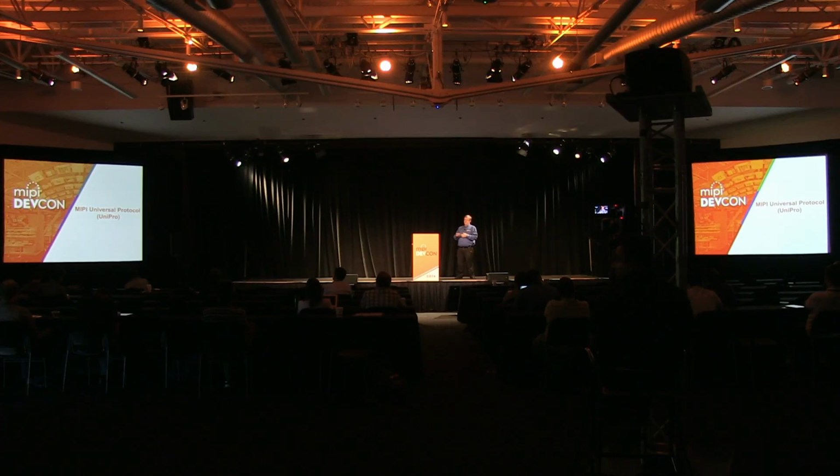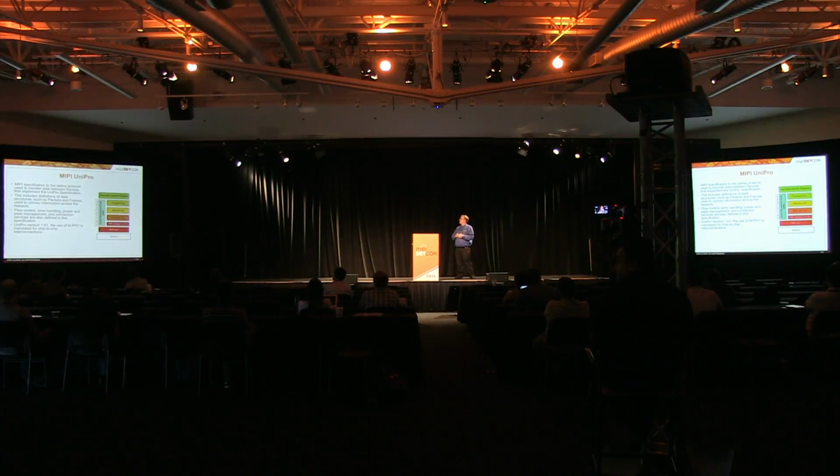So with a UniPro problem, what would you see in UniPro context if you had a signal integrity problem? You may see nothing, or you may see errors happening randomly through the traffic. Or is the problem really something that's happening at the upper layers? Is it a software problem? Is it related to flow control or buffering of the packets? That's where you always want to define where that is before you try to debug the problem.